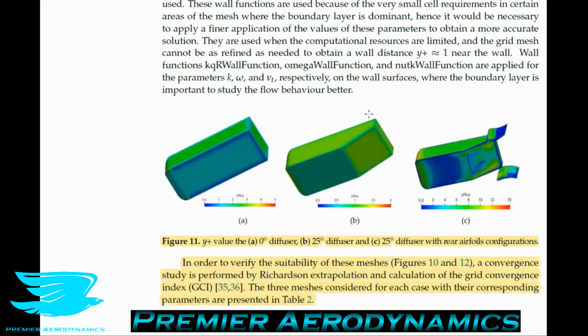Now, in figure 11, they talk about the Y plus value. The Y plus value is very important, and not every CFD simulation needs a Y plus value of 1 or less, but ideally, if you do get a Y plus value of 1 or less, you really don't have to think about whether your results are good or not, because you know that they will be good. You're using the right equations in the right resolution. If you know what you're doing, you could always use a coarser Y plus, but you do run the risk of potentially getting it wrong.